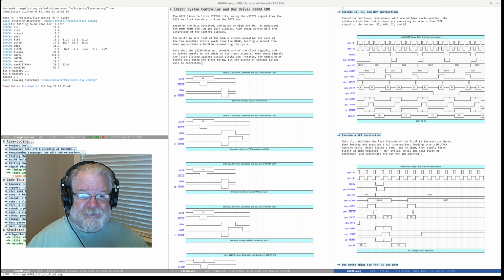Goes in the instruction register. It's a no-op, so we do nothing, and then we go on to the next instruction. Instruction at address 2 is F3, which is disable interrupts. Boom, F3 comes in. We disable interrupts. What do we see up here? Oh, here's our interrupt enable pin, and interrupt enable goes low. We cycle through, we do another enable interrupts.